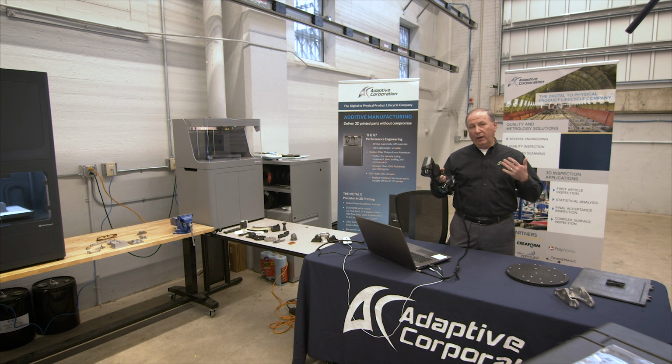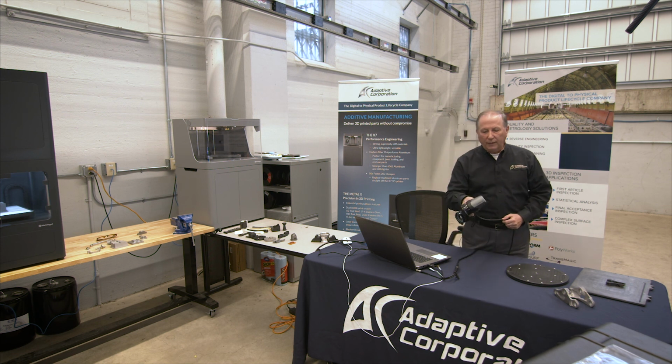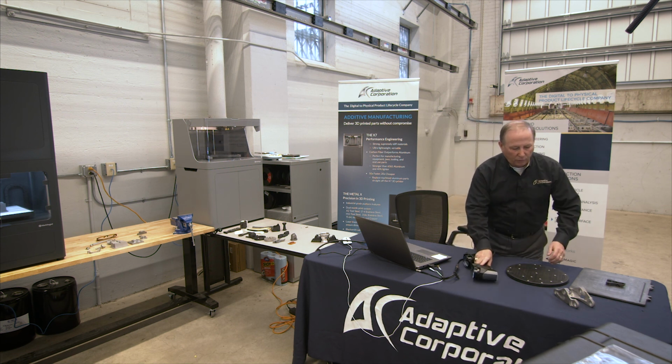If you compare that to a CMM, depending on the CMM, it is always going to be the highest accuracy measurement device you can get. CMMs are typically maybe 2/10, 3/10, somewhere in there. They're very, very accurate measurement devices. Most arms are 7 to 9/10 of a thou. This is 9/10 of a thou. So in terms of parts, it really opens that up to a lot of options.